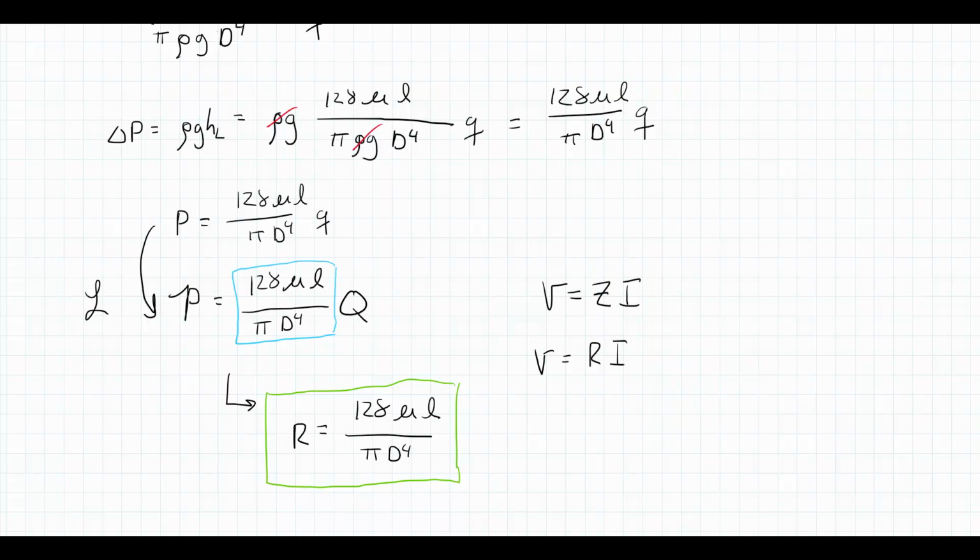And again, the restrictions on this being the equivalent resistance: this was derived for a circular pipe, because that was the specific Reynolds number calculation we used. And this is for laminar flow only, because the Moody friction factor that we used, that 64 over Reynolds number, was coming from laminar flow. So once again, if you have a turbulent flow, this is not the equivalent R to use. If you have a non-circular cross-sectional pipe, this is not the R to use for that.